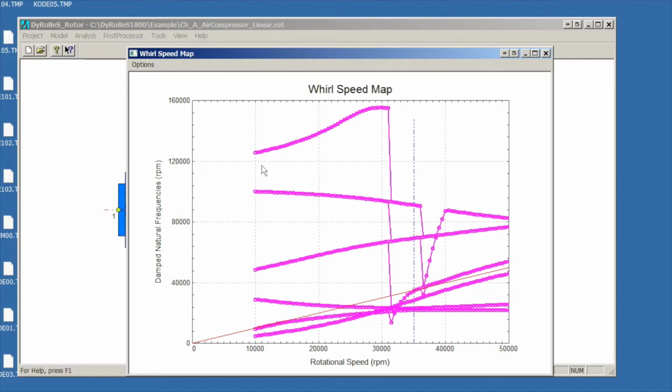What the curve fit option does is it connects the little dots, the speed points that we calculated at, by mode number. So this is all mode number 6. At this point here, at around 32,000 RPM or so, 31,000 RPM, another mode comes into being. So there's a mode that's this mode here. It drops down to 0 at just around that speed. So above 32,000, this becomes mode 1 instead of that, which means that this is no longer mode number 6. That's now mode number 6.